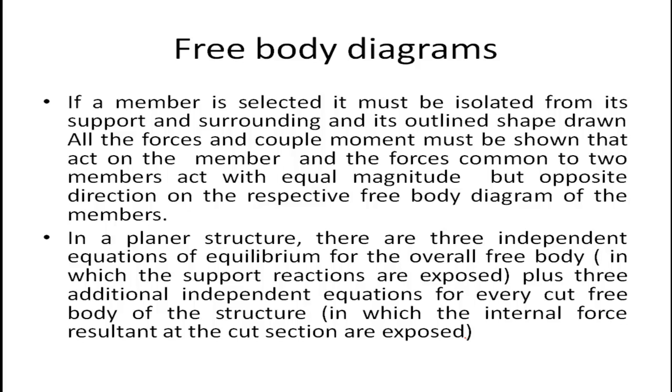And in a planar structure, as you already know from the previous slide, there are three independent equations of equilibrium for the overall free body, in which the support reactions are exposed, plus three additional independent equations for every cut. Remember this: for every cut there are three additional independent equations for the free body diagram of the structure, in which the internal force resultant at the cut section is exposed.